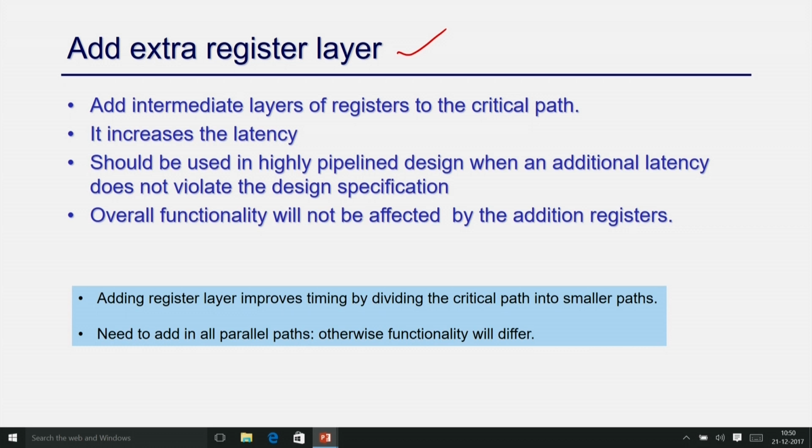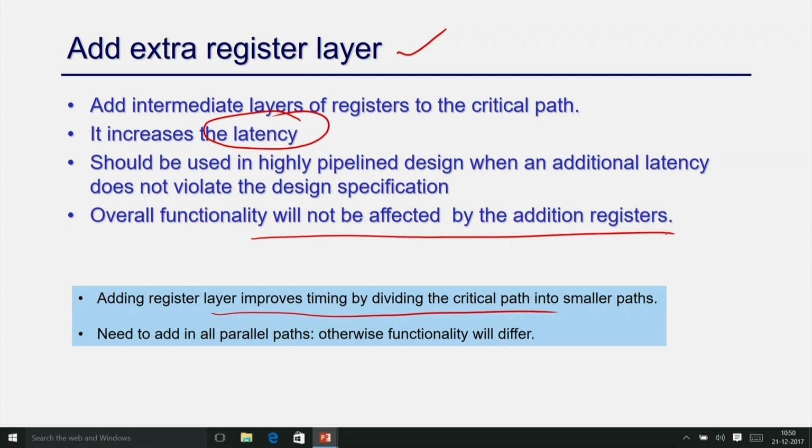So, what I just said is that adding a register layer improves the timing by dividing the critical path into smaller paths. But it also affects latency: obviously the latency is going to increase because you are adding registers to your design. You have to be careful about this.